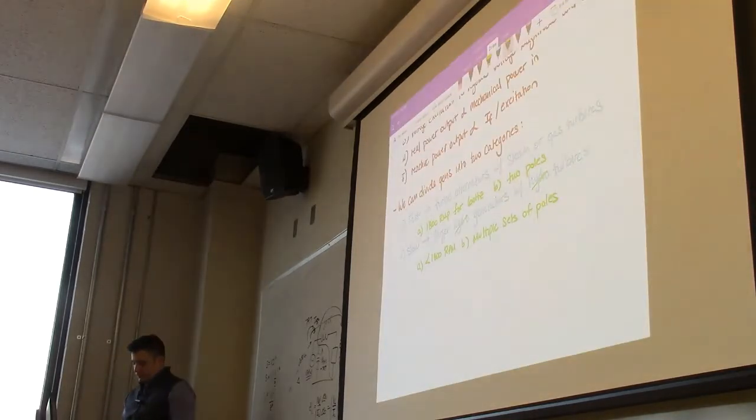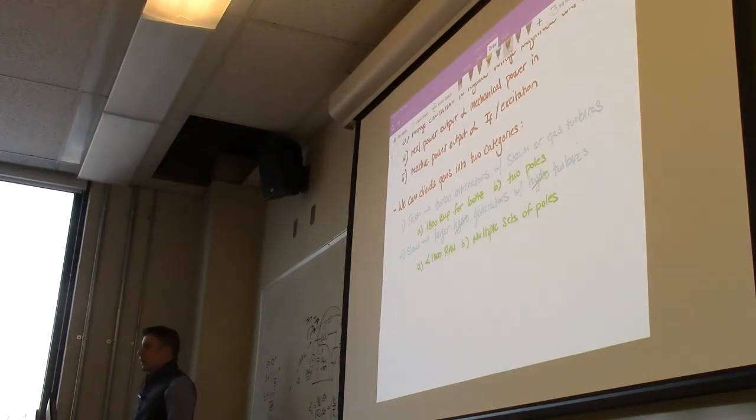So ever try to go over 1800? Well, the thing is that you can use multiple sets of poles to take a slow mechanical frequency and make it a faster electrical frequency. You don't really ever want to generate more than 60 hertz unless you're talking about some very special system which runs on high frequency AC, and I don't really know of anything that does that. It's possible. I just don't think there's a real application for it.